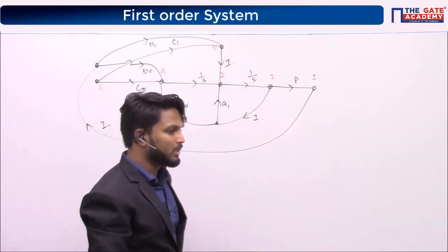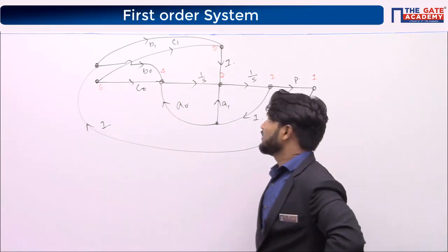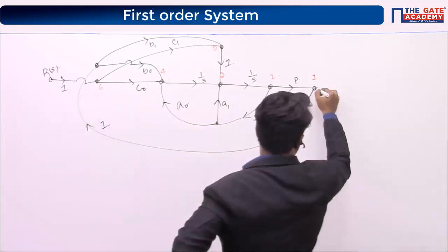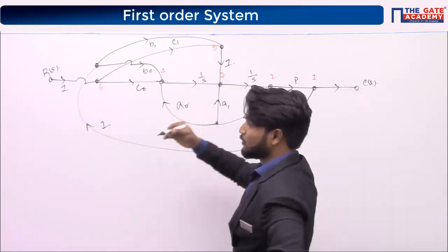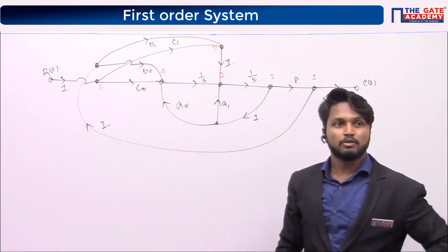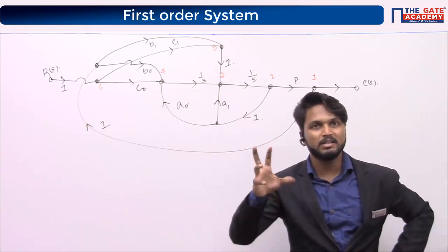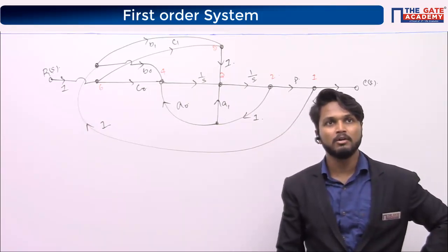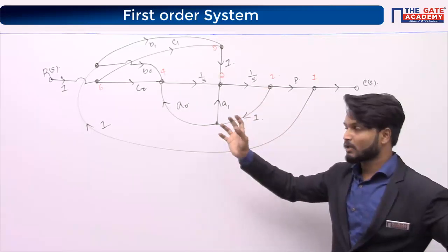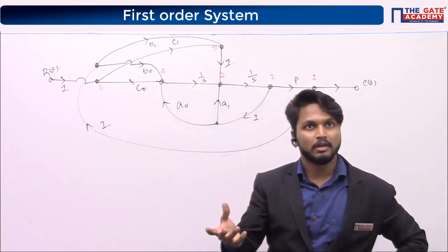So where are we giving the input? Input we are giving at C0 and C1, which means this is your output. Once you get the signal flow graph, you will get everything, right? You can rearrange the block diagram in a simplified manner also, and then also you can get it. So once you get the signal flow graph like this, you will get the overall transfer function, right?